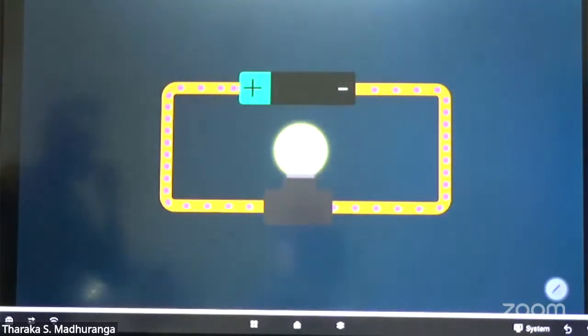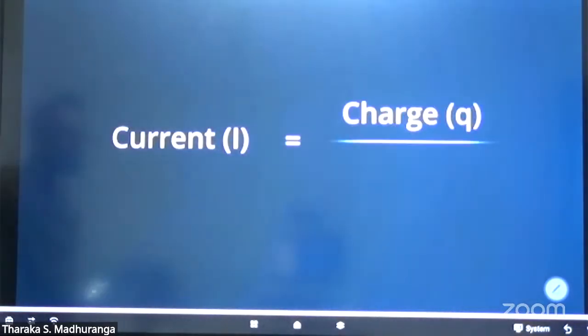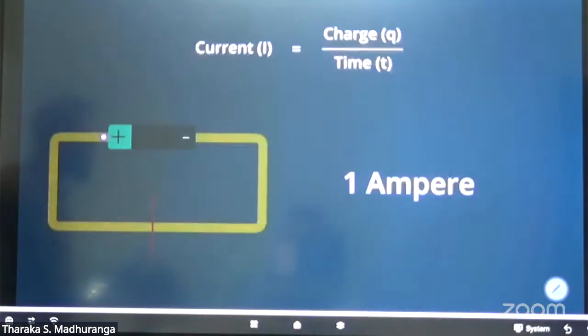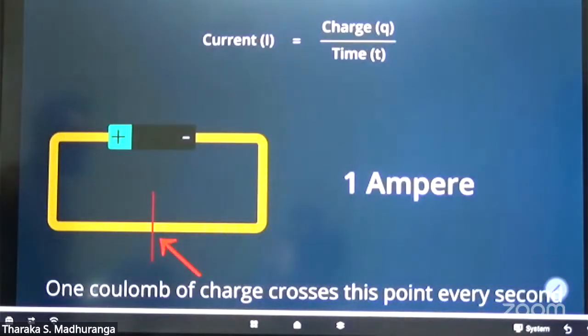When these coulombs of charge move through materials, such as in the wiring of our homes and devices, we see effects like light bulbs illuminating. This movement of charges over time, that's electric current. Mathematically, current, represented as I, is the charge Q that flows, divided by the time t it takes. So a current of 1 ampere means 1 coulomb of charge flows every second.